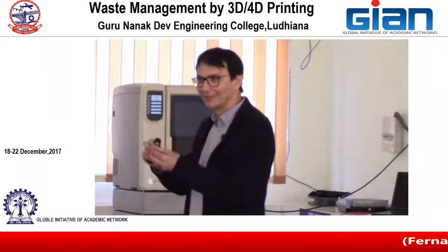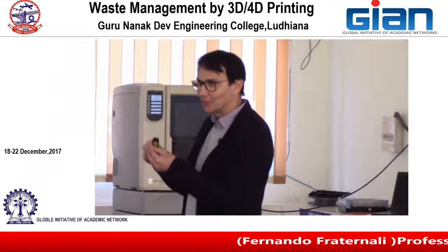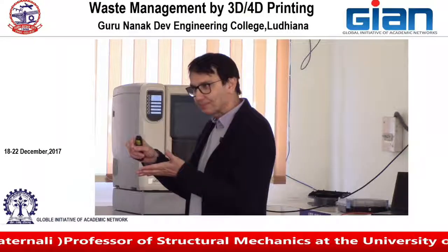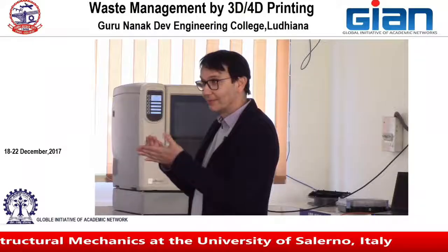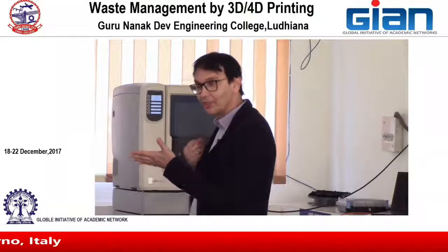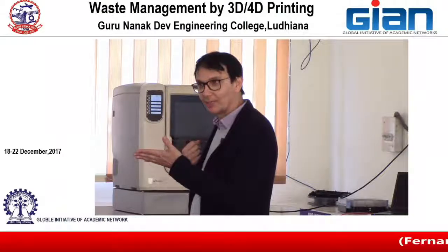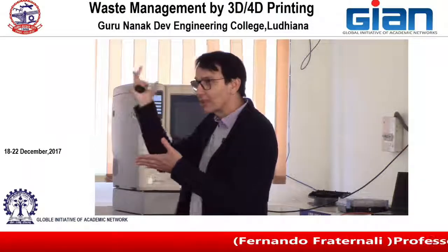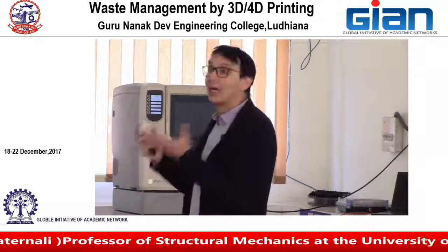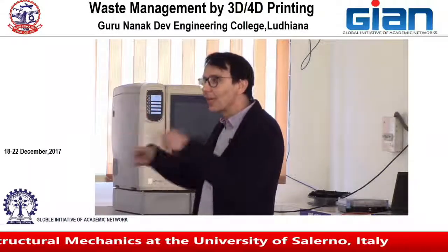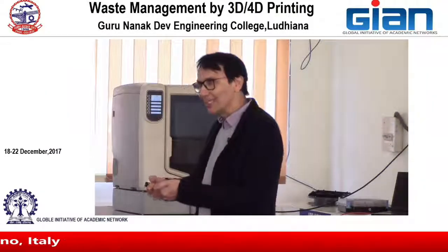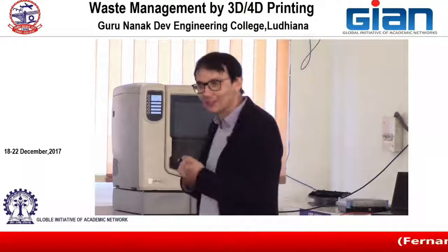You remove elements. You remove one element because in our model, gamma kills the element. If we damage an element, it's like removing that element from the finite element model. If it is cracked, it doesn't exist. We remove it. But we have to try removing the elements and seeing if the energy decreases.